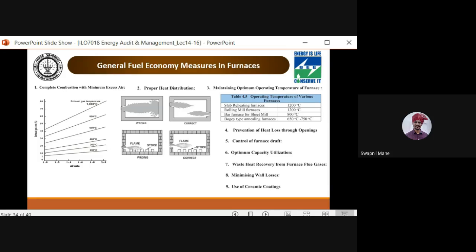Okay, so T is the absolute temperature into area, then refractive index of the refractories. All these things will come into consideration. The time of operation, everything multiplied together will give you the total heat loss through openings. How much time the opening was, the inlet or outlet of the furnace, was open for inlet of material and outlet of collection of the finished heated product.